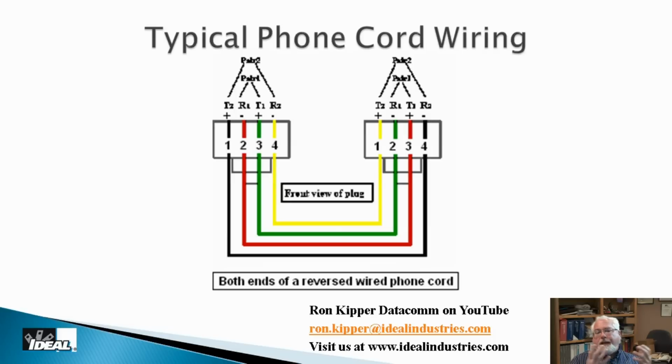So today, though, you know what? Digital phones are really not polarity sensitive, so they really don't care. If you straight through wired, a digital phone should work. The reason these still are is because people still have old analog phones, and those things were made back in a time frame when we were proud of what we made, and they were designed to last years and years and years. So as I said, you can go out and buy a phone out of the 40s or 50s and still use it today, as long as you got pulse technology coming into the building. Okay.